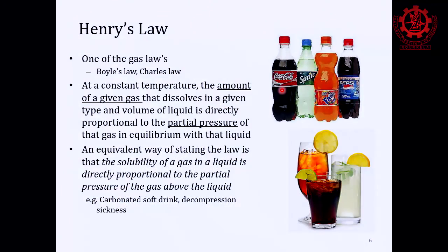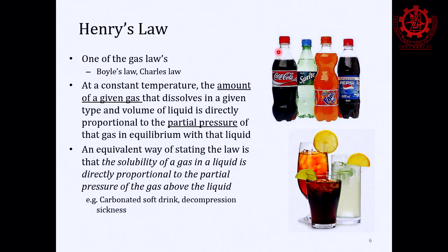So if you bring it to room temperature, what happens to those gases? They come into the head space, right? If a lot of gases come into the head space, some of them can permeate out of the package. So that's why, to preserve these, it is better to keep them at low temperature. And that's why you have a shelf life of 3 to 6 months for these bottles, because at room temperature, the level of gases dissolved in the liquid is less, as most of them are in the head space.